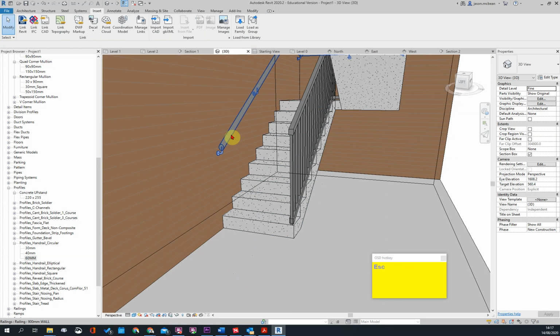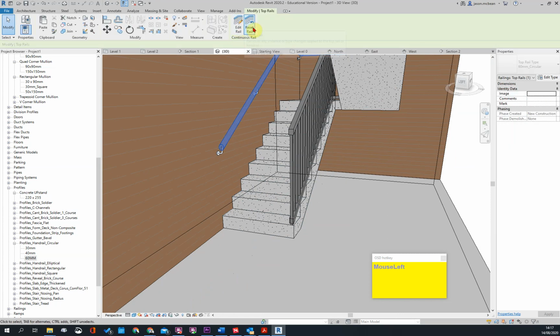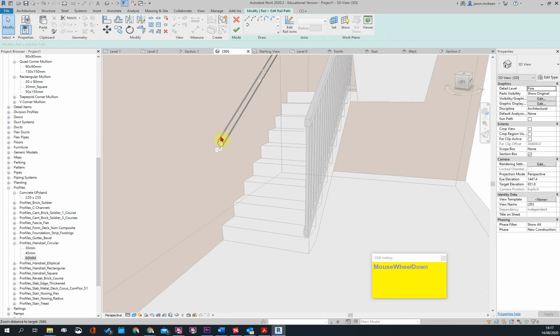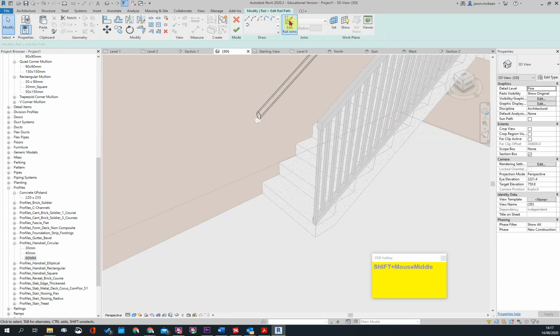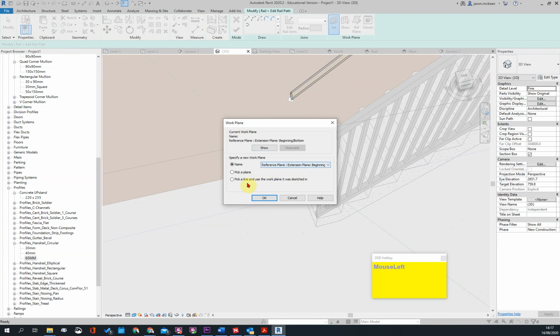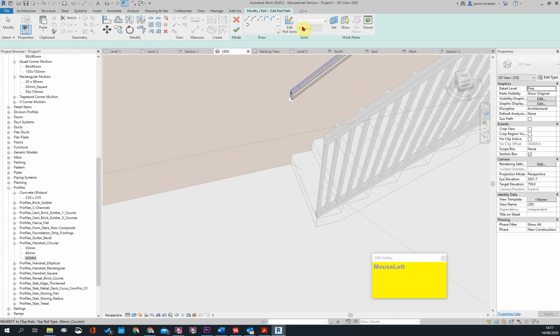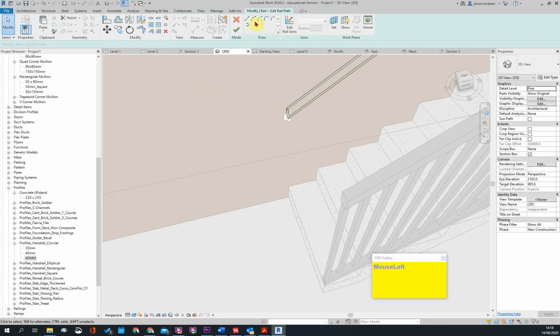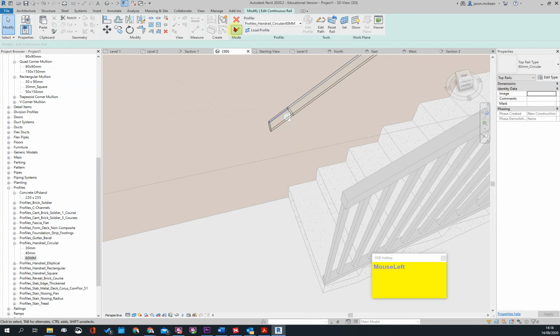And then because you've got a railing, you can say edit rail. What this allows me to do is extend the path of the bottom rail. So I can pick set, and I want to pick this wall, for example. Finish. So pick path, I just want to extend the path a bit. I want to extend the path from there down, and then finish command.